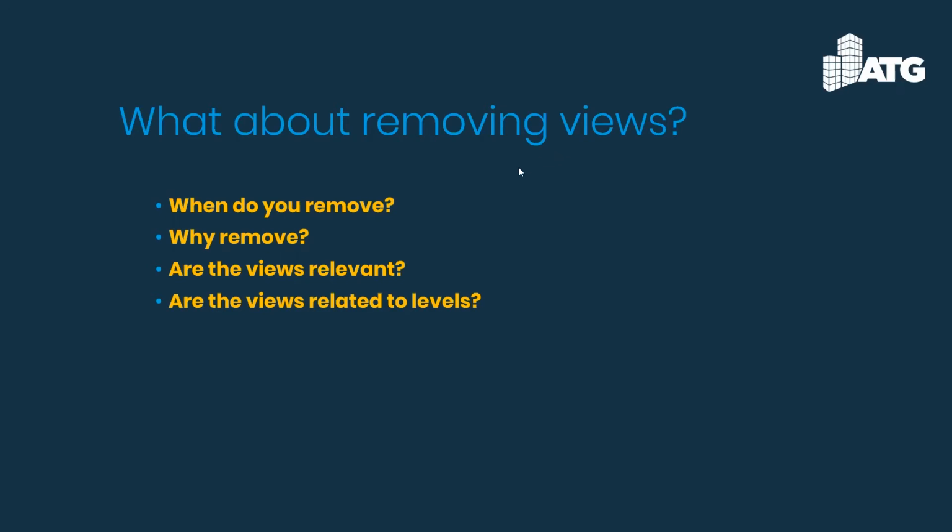They just continue to create more and more of those. The other thing that I see a lot of is creating camera views. Camera views can really increase the file size of your project. So it's a handy tool to use, but if you're just using it to check something, once you're done with it, delete that 3D view out.